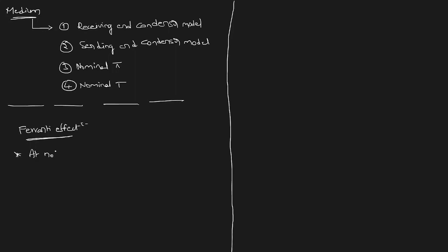At no load or lightly loaded conditions, I mean load should be either zero or lightly loaded, the magnitude of the receiving end voltage will be greater than the magnitude of the sending end voltage. Such a condition is called the Ferranti effect.